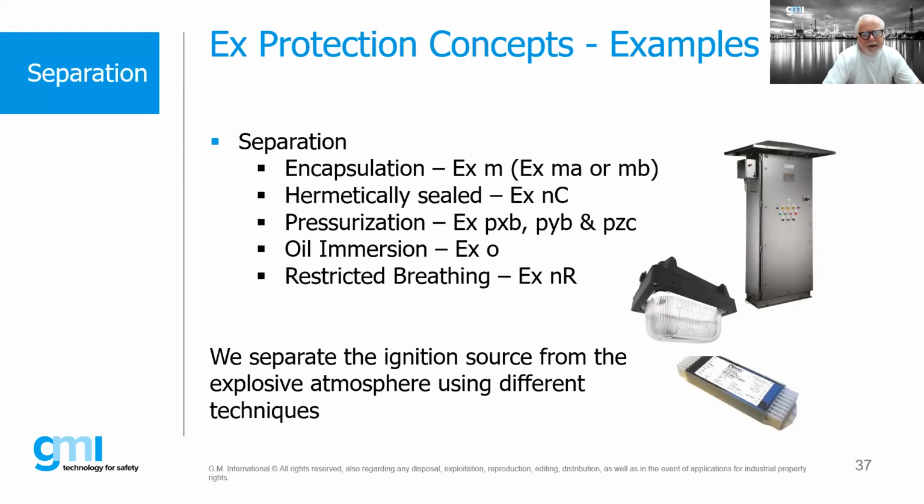So we really have to understand what product it is, to see what our options are with regards to the various protection concepts. And also understand this, not all protection concepts are suitable for all zones and gas groups, T codes, and specifically the ambient as well. So there's a little bit of engineering and design work that we need to do up front before we start selecting equipment for use in these areas.